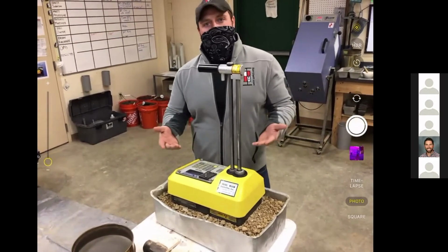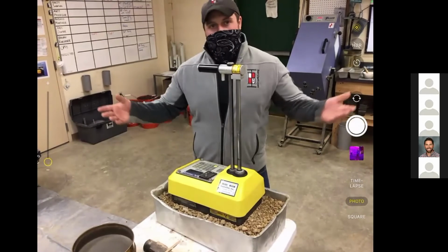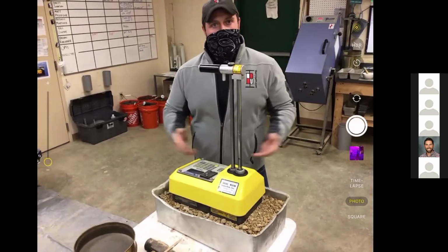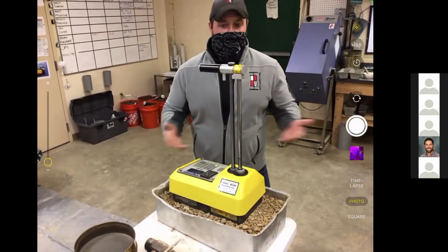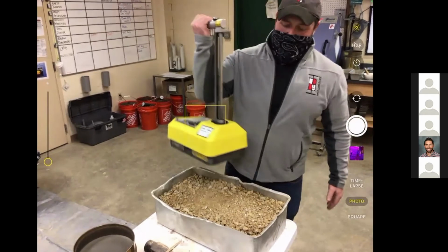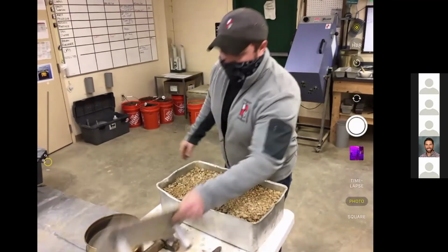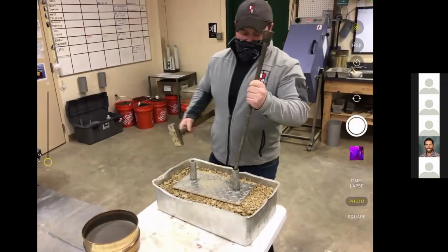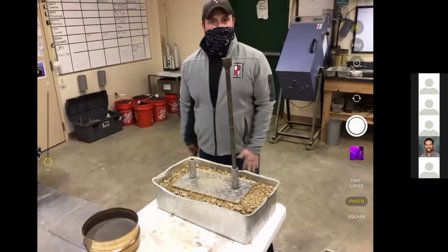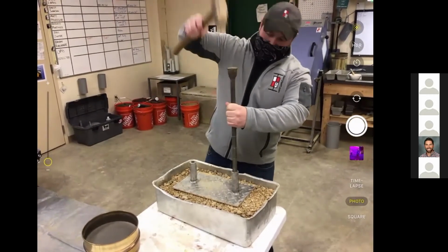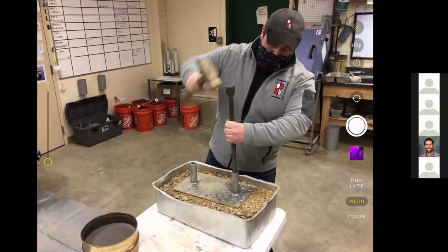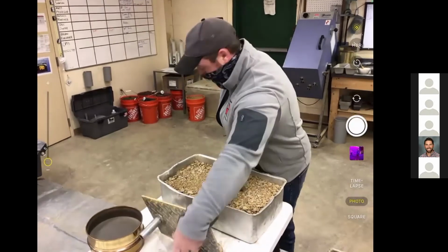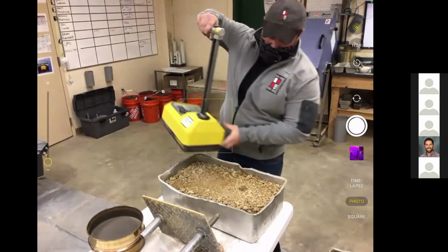So once you're on site, the pan operator, whoever's out there, they put a lift of soil down, they'll roll it in. We'll monitor that and watch it. Once they're ready for us, we'll actually step out, get the gauge. We have a base plate, a pin, and we basically go at different locations throughout that whole pad area. And we can actually pound this pin into the ground and then pull this out. And we're ready to actually test.